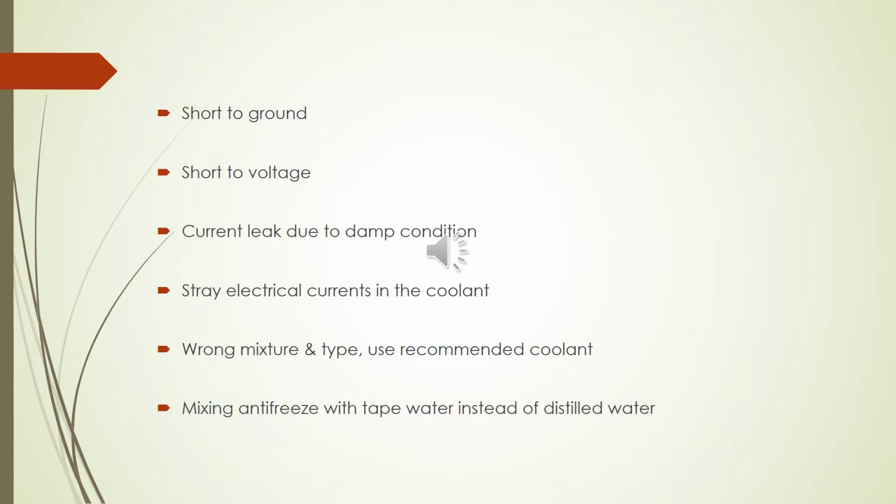We are still on the causes of electrolysis or galvanic corrosion. Another point is short to ground, short to voltage, current leak due to damp condition, stray electrical currents in the coolant, wrong mixture and type. You are supposed to use the coolant recommended by the manufacturer. Mixing antifreeze with tap water instead of distilled water.